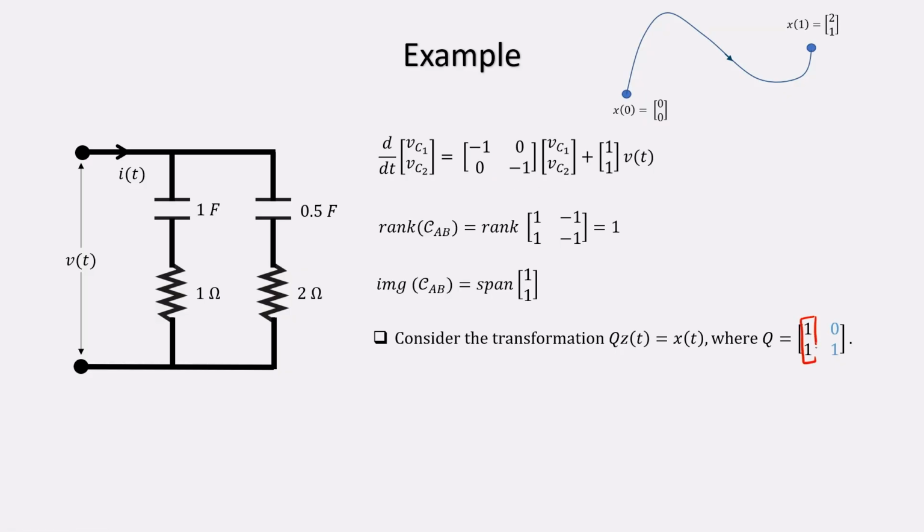The first column here is B, and this is your r here. So, that means B, A B, up to A to the power r minus 1 B, and since r is equal to 1 here, I will just have one column for the controllable part. So, (1 1), and then I can choose anything for G1 so that the Q matrix becomes invertible. I chose (0 1); you can come up with anything else also.